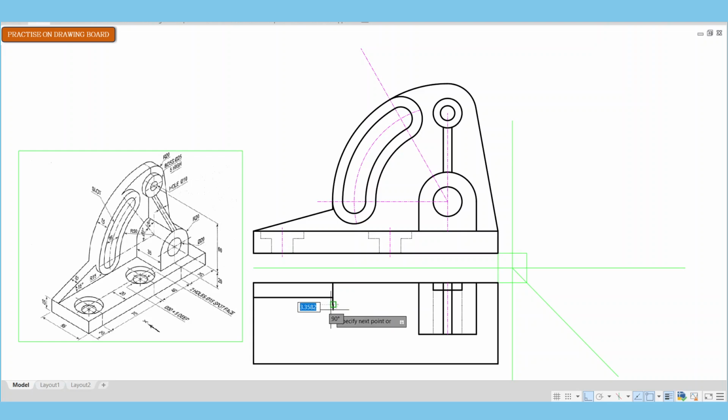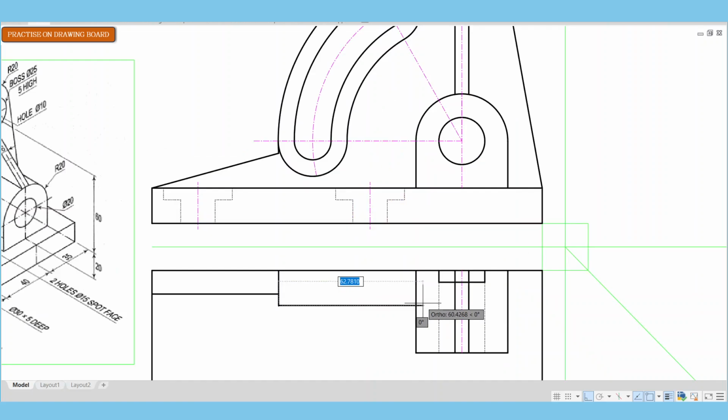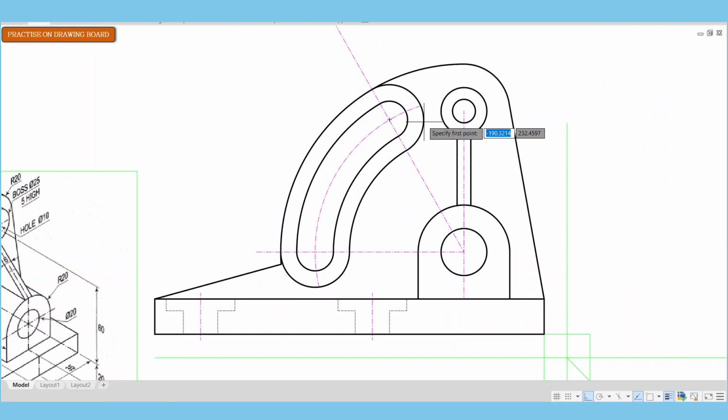Now the slot protrudes by a distance of 5 from the slant part, or from the thickness. So I measure 5 away from the slant portion, or the thickness of the upper part. Then I project the other end of the slot downwards.